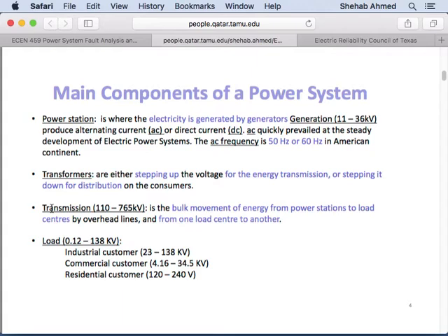So it's like a transformer. You can think of it as a DC transformer, right? At the end of the day, a transformer allows you to connect two systems with different voltages, but they have to be the same frequency in the case of a transformer. If you use power electronics, you connect two systems, but they can be different voltages and different frequencies, right? Or they can be similar frequencies, but not synchronized.